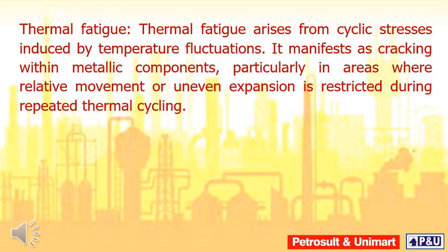Thermal fatigue arises from cyclic stresses induced by temperature fluctuations. It manifests as cracking within metallic components, particularly in areas where relative movement or uneven expansion is restricted during repeated thermal cycling.